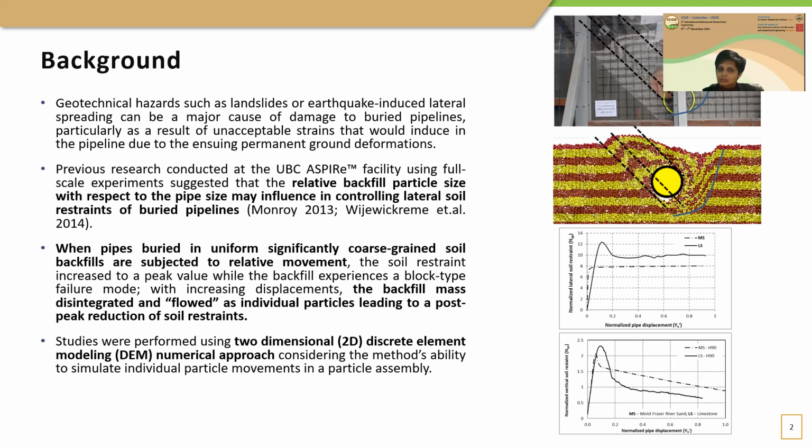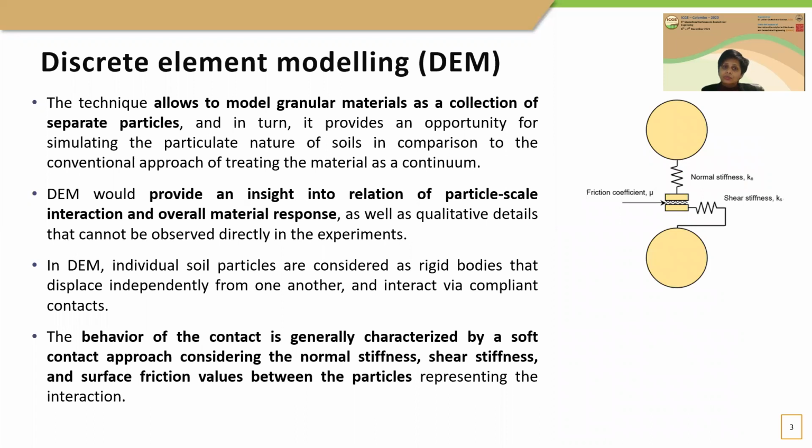However, we had two challenges. We needed to study the effect of particle size, and also we needed to model the flow of individual particles. So continuum modeling was not an option. Therefore, we decided to use discrete element modeling. As you all know, the discrete element technique allows us to model granular materials as a collection of separate particles. In turn, it would provide us an insight into the relation of particle-scale interaction and overall material strength. Therefore, it is well suited for this study.